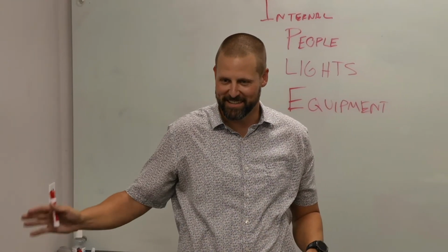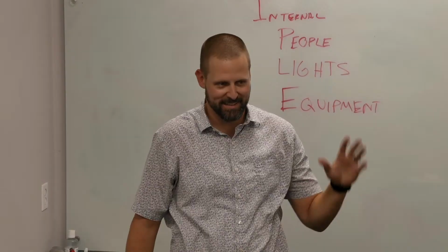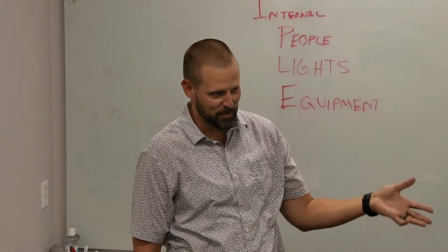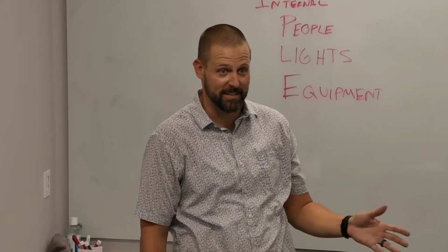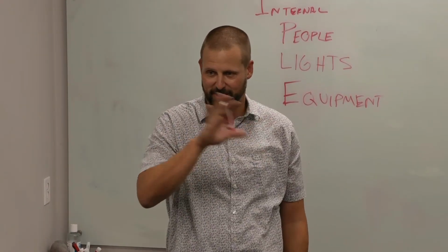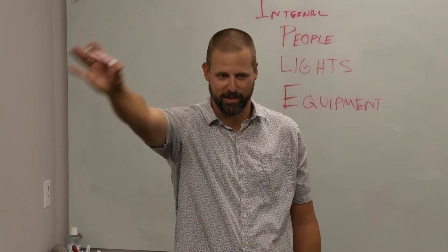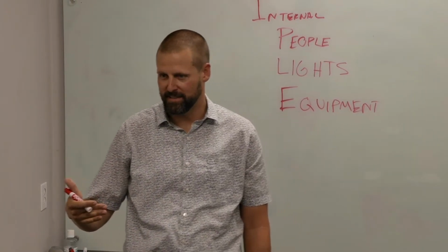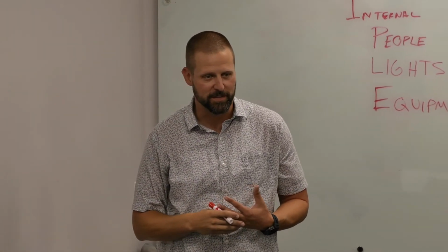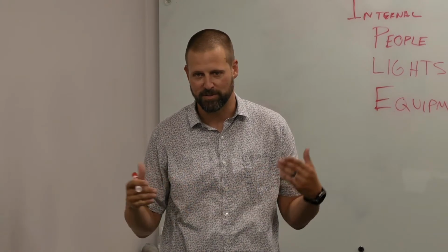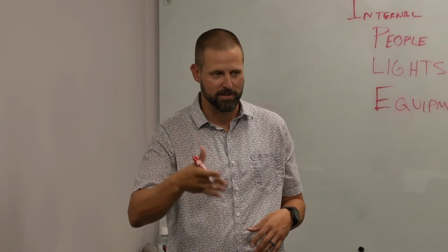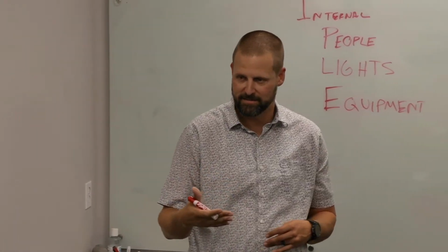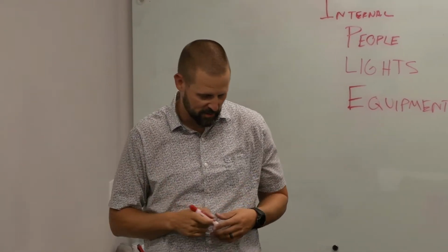So in the morning, the eastern exposures are going to get more sun. In the afternoon, the western exposures are going to get more sun. And the south is going to see the sun all day, because the sun kind of goes across the south face of your building. And the north, we often treat as just shaded, or we use the north wall as a placeholder as a shaded assembly, because the north doesn't get direct sunlight, typically, because it's shaded by the rest of the building.